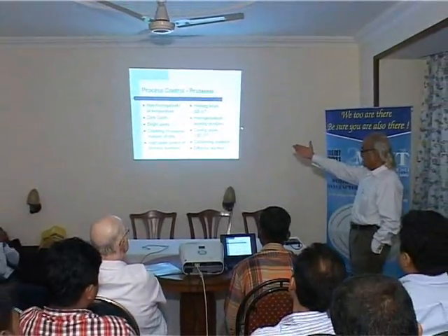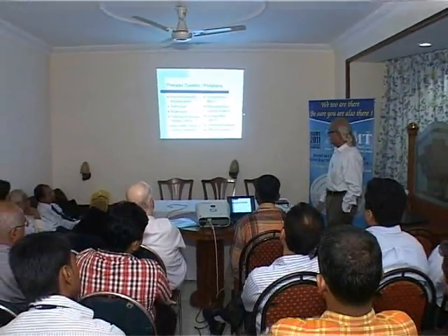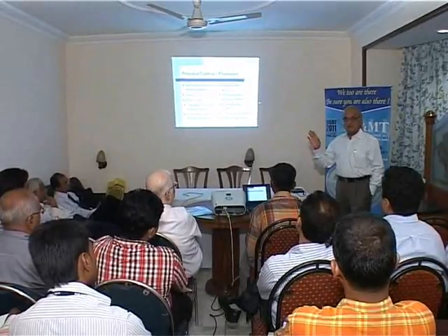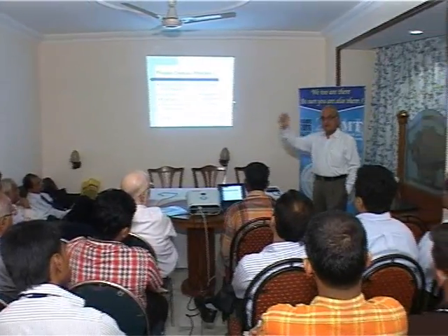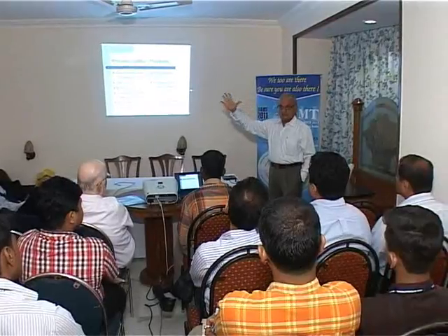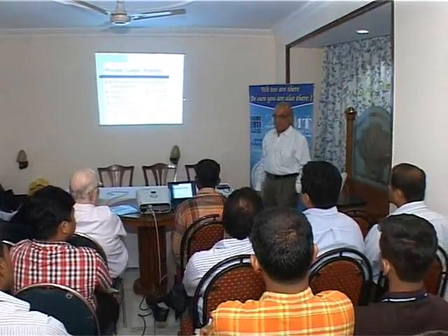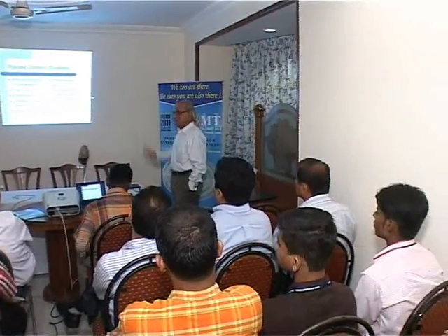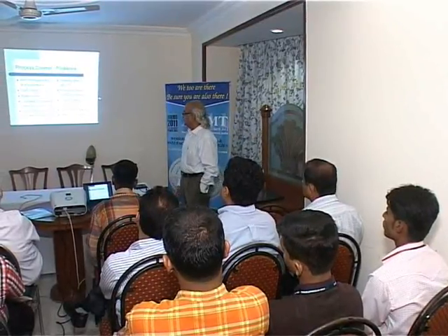Now this is the fourth bullet on the left side. My furnace doesn't have a full load there, so, Raj bhai ka bhi dal do, Pradeep bhai ka bhi dal do. One is 2 kg, one is 15 kg. This kind of clubbing of jobs ruins the quality of your heat treatment. Next.